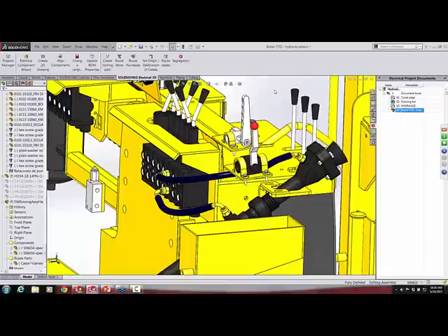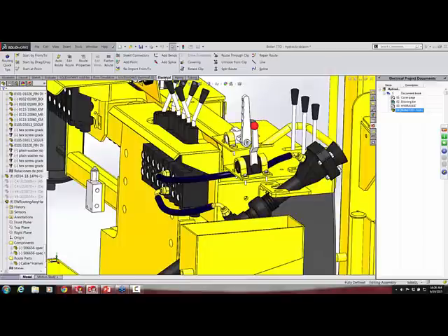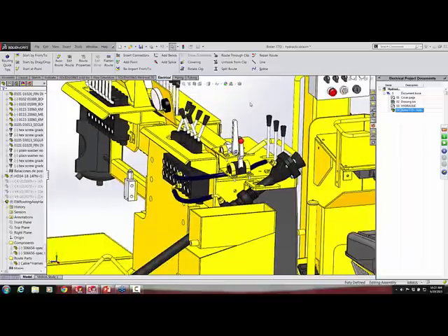To flatten the harness, I can go to my electrical tab. And electrical, again, that's kind of what I was talking about a little bit earlier. Electrical is actually part of the routing that's part of SolidWorks Premium. But this electrical also comes with the SolidWorks Electrical 3D. The SolidWorks Electrical 3D does not include the piping and the tubing, so that makes it a little bit awkward when you're trying to create tubes and physical pipes with L-weld elbows and things of that nature, if you don't have the SolidWorks Premium to go along with SolidWorks Electrical 3D.